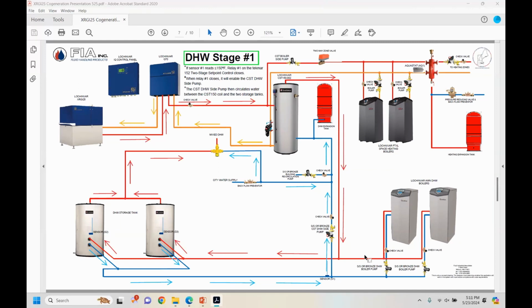So we're going to have similar operation for heat pump chillers. In this case, the only way to create a return for a lot of these more modern technologies, when we're incorporating them into the systems, which a lot of times people are doing, because a 100% approach to some of these more expensive technologies can be so costly that they prevent the projects from moving forward. So you start seeing hybrid approaches. In this case, obviously, this isn't so much hybrid because they're both gas products. But let's say if this were a high temperature heat pump of some sort, what we would do is we would stage equipment. That's the best way to get the best of both worlds.